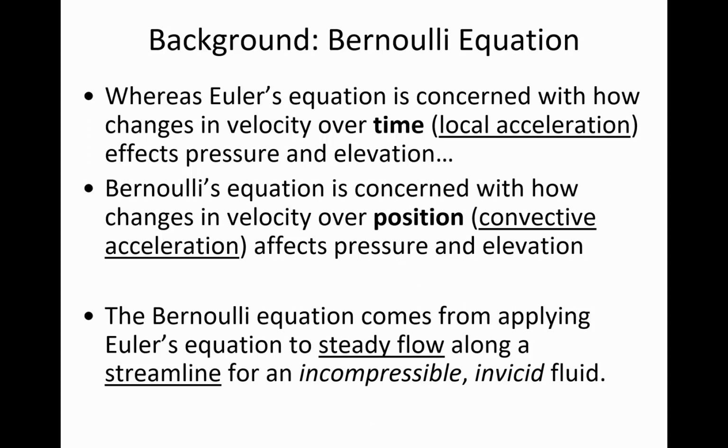So for example, a gas, just like atmospheric air, has relatively low viscosity compared to corn syrup. You know, the fluid that was used in that first illustration with the ultralaminar flow. The reason why he used the corn syrup is because it has so much viscosity, it helps to keep the fluid from mixing. So Bernoulli's equation, if you apply it to a fluid that does have viscosity, it's going to introduce some errors. And the reason why we have this inviscid fluid assumption is because Bernoulli's equation has no way of handling energy losses due to pipe friction.